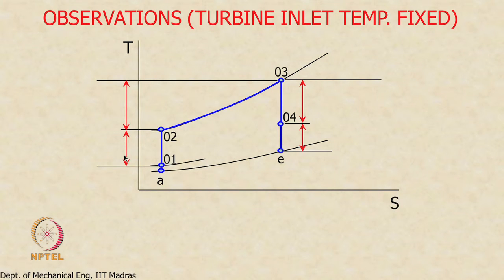This is compressor work. Now the compressor work will also change because we are increasing the pressure ratio. So this is the earlier value for compressor work and turbine work, and this is the fuel flow rate, and this was the thrust that we had earlier, and we have all these other quantities. So the baseline quantities are indicated in red here. What will happen when I increase the pressure ratio?